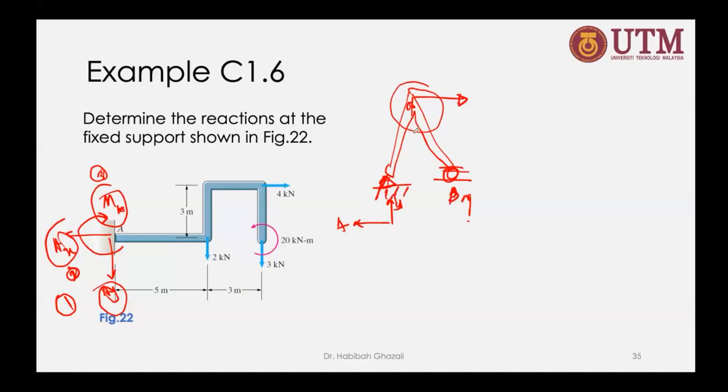Remind me, I have found this question that students have problems with when they start putting in all these reaction forces. What you learn from statics is that you have to dismember the frame and draw the free body diagram of this or that to solve it. But look at this frame as a whole first. Put in all the reaction forces. If you have 3 reaction forces, you have 3 equilibrium equations. You can solve it straight away.